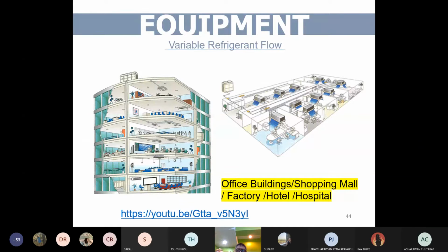Okay, last time the price of the VRF was almost double that of the chillers. At the moment it's cheaper. I can use a rule of thumb like 5 baht per BTU or 4 baht per BTU, including installation. Comparing to the chillers, chiller is about the same, 5 to 6 baht per BTU. But the chiller has to be a big, large system.